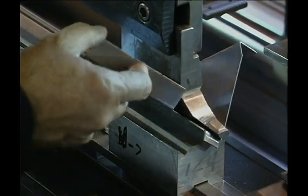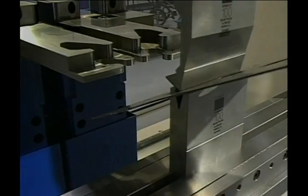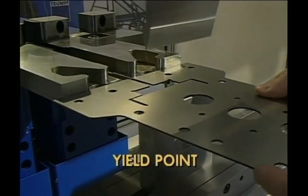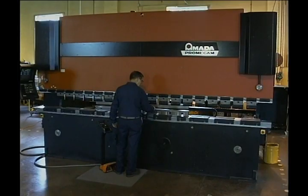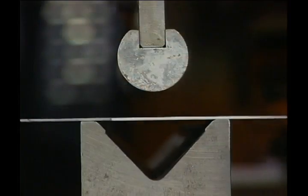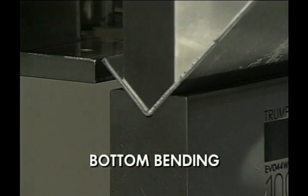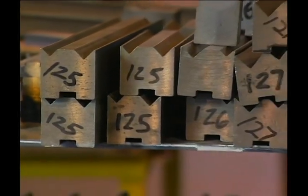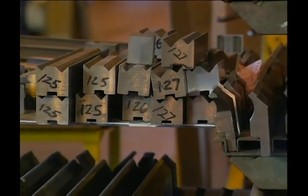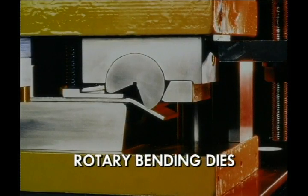Bending is the creation of three-dimensional shapes out of two-dimensional material. Bending is a method of producing shapes by deforming the metal beyond its yield point, but not past its ultimate tensile strength. The press brake is the most common kind of bending machine. There are two major categories of bending: air bending and bottom bending. 90-degree V-shaped dies are the most common type of bending die, but many other types are used to produce shapes, such as acute angle dies, gooseneck dies, offset dies, and rotary bending dies.